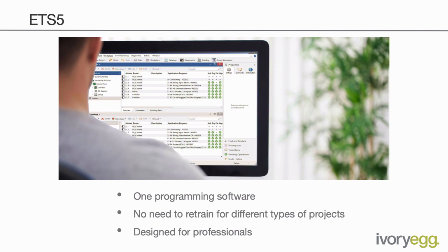The ability to program a huge range of products from different manufacturers doing different functionalities, but always being updated, adding new features like KNX Secure, which enables us to encrypt both the messages on the bus, but also the entire IP layer if we're doing an IP KNX backbone, for example. So adding these new features means that KNX is always kept up to date, but we have this look back in terms of backwards compatibility with previous versions of the system.